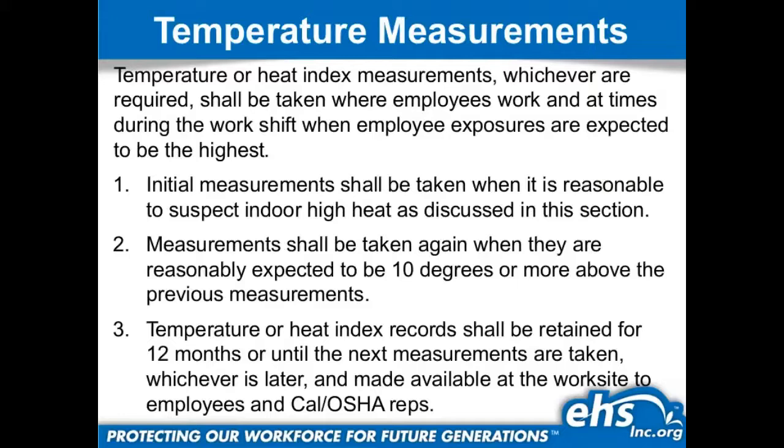Everyone's always looking for that shortcut. That doesn't mean we're doing our temperature measurements at 6 a.m. when we know that work environment is going to be at its coolest. We need to hope for the best, but plan for the worst in this one. We are taking our measurements at the highest temperature. If that means we're doing multiple readings through the day to get a gauge on that, then so be it.